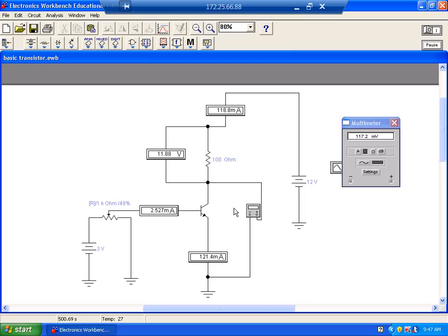It's just like the diode. You know, the diode has a breakover voltage, right? If you exceed the breakover voltage on a standard diode, then it's usually bad. So if you break over a transistor, it's bad. So right now we're operating in saturation. So if I want to turn things on and turn things off, then I'm going to operate it between saturation and cutoff. Now I'm operating it in the active region.